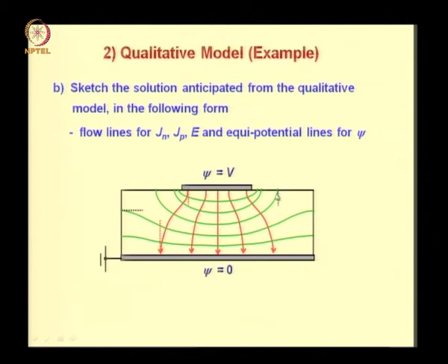So the potential lines or equipotential lines emanate perpendicular to the non-contact surfaces. You can see that here as well as on the sides here. What is the reason? The reason for this is that the electric field is perpendicular to the equipotential lines, and we have said that the ambient dielectric constant is 0, therefore no field can escape normal to the surface into the ambient.